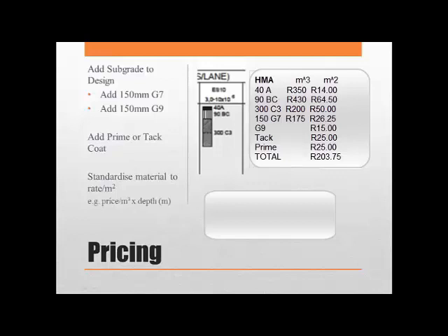So where we are putting down, for example, a 40mm asphalt layer, all of those catalogs will have the same wearing course and the same subgrade. So the price comes down to the base and the sub-base. So when you're costing, this is really where you need to cost in our design context. You make your final selection and then you add your subgrade for a final price.